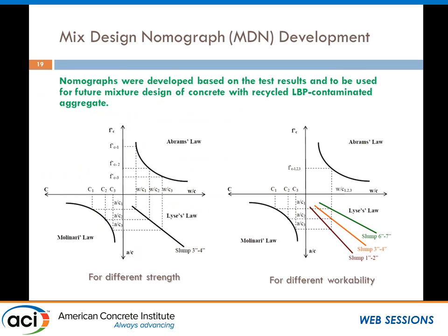Okay, one other thing we did is based on the different types of aggregate we use, because we use different aggregate to cement ratio, different cement content, different water cement ratio. We're trying to figure out if we can provide some guideline, with this specific aggregate, on what you can follow for a mix design. I don't know how many of you are familiar with the nomograph for mix design, but a quick review is that you follow these 3 laws.